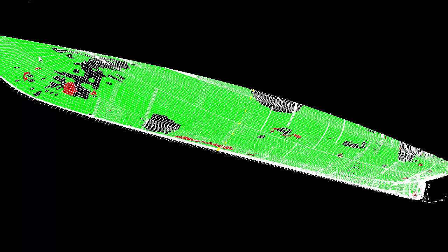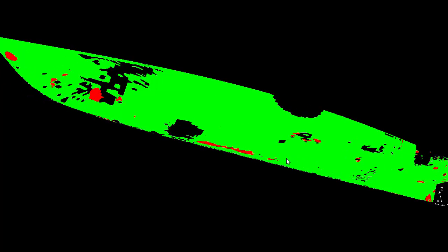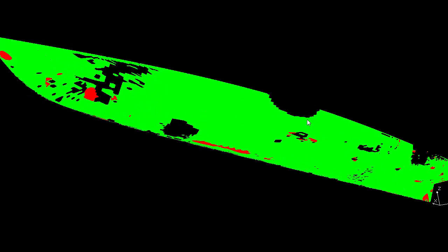We'll get rid of, again, the curves to come back, so get rid of those. We'll get rid of the mesh, and here we can see we've got some shading. We've got some blank areas where the density of the point cloud is not dense enough to draw a conclusion to the position of the surface, so there's not enough statistical data in that area.